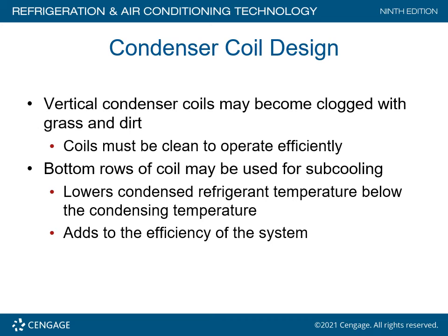Condenser coil design. Vertical condenser coils may be clogged with grass and dirt. Coils must be cleaned to operate efficiently. Bottom rows of coils may be used for subcooling. Subcooling lowers the condensed refrigerant temperature below the condensing temperature, which adds to the efficiency of the system.